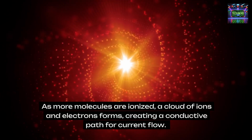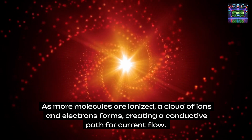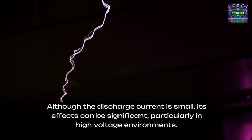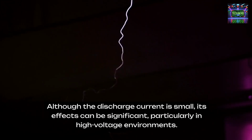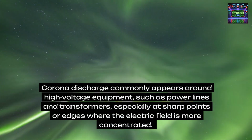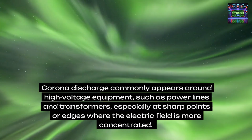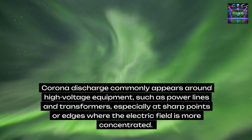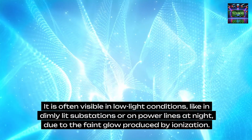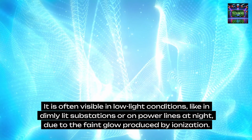As more molecules are ionized, a cloud of ions and electrons forms, creating a conductive path for current flow. Although the discharge current is small, its effects can be significant, particularly in high-voltage environments. Corona discharge commonly appears around high-voltage equipment, such as power lines and transformers, especially at sharp points or edges, where the electric field is more concentrated. It is often visible in low-light conditions, like in dimly lit substations or on power lines at night, due to the faint glow produced by ionization.